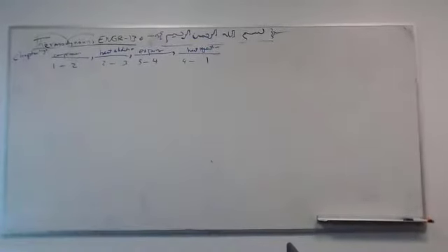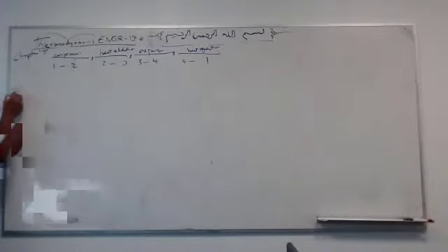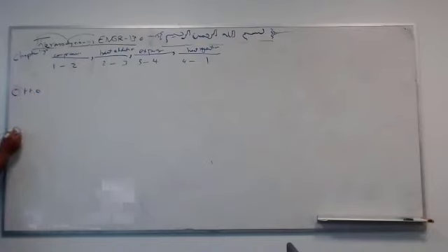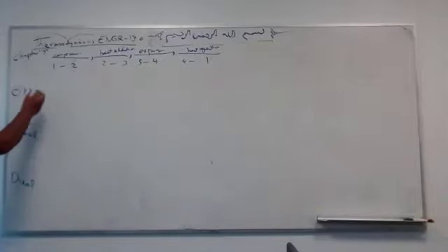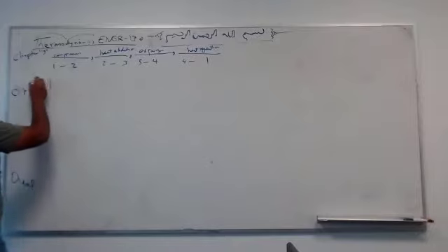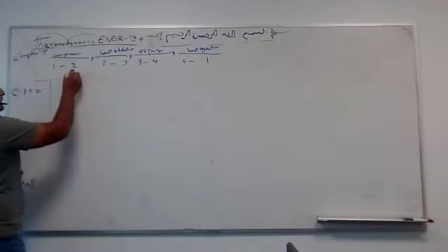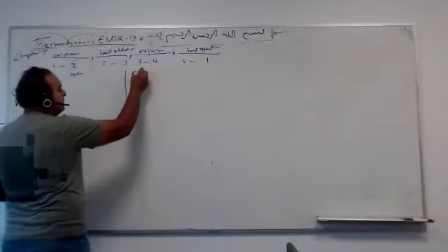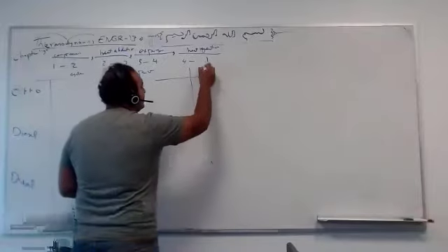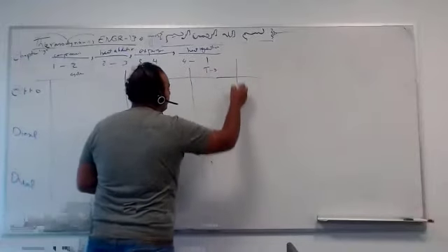So for all these cases, guys, all the designs, Otto, Diesel, Brayton, Rankine, all of them, we have compression, heat addition, expansion, and heat rejection. Maybe a different system or even cycle, but these are the four steps for all of them. Let's talk about the first one. We have either a PV diagram or a TS diagram. Otto, we have Diesel, and we have, let's say, Dual. And of course, before them, we have Carnot, the 9.1, 9.2. So let's start with the cycle, and we have the PV and we have TS, and if you want to get the ideal efficiency.